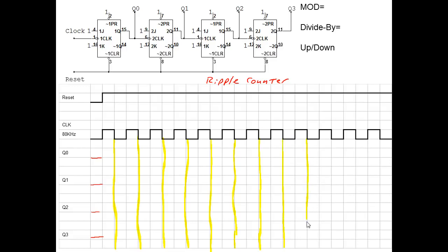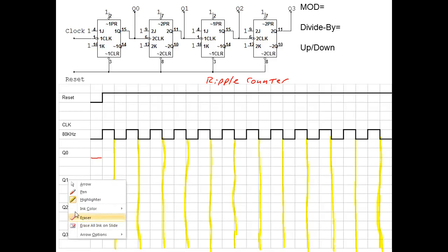It's a lot of pulses here, and actually we won't even see all the changes. We could have had room for maybe 17 or 18 pulses. We would have seen all the changes go back from one number to the other, but since we don't, we'll go with what we have here. Okay, so these are going to stay low over to the next negative edge. At that negative edge, then we'll do something.